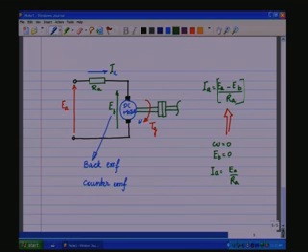RA is a very small quantity, because it is only the armature winding resistance. So, IA will be orders of magnitude higher than the rated armature current value of the DC motor. So, initially you will see a very huge current surge due to the fact that there is no back EMF, and then as the current flow produces the torque, the shaft starts rotating, and a finite speed comes into being, which will induce EB, the back EMF, and this back EMF gradually rises as the speed picks up.